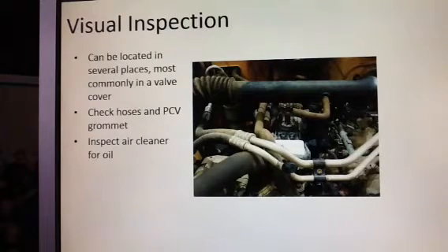If we think we have a PCV valve that's having a problem, we can look right around that PCV valve. Make sure we can take it off, we can shake it, make sure it's actually moving up and down, the ball inside is moving, make sure it's in there, make sure it's not broken, make sure this hose is connected up to it. So simple visual inspections that we can do with this.